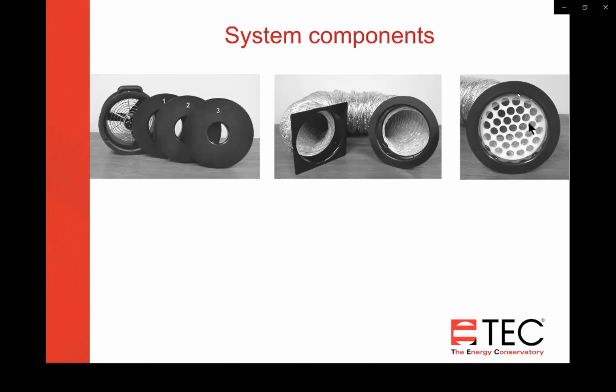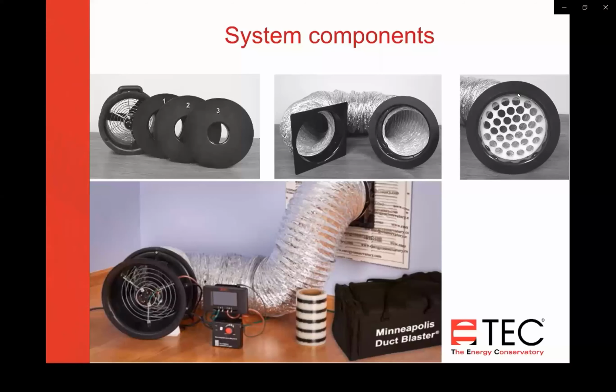You want to connect a tube there, and that's measuring the pressure inside that duct in a few different locations. And if you don't have that flow conditioner pushed all the way back in there, you won't be reading the pressure inside there. So it's important to get that pushed back.